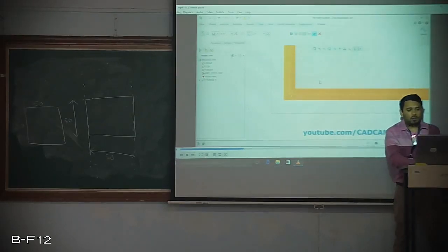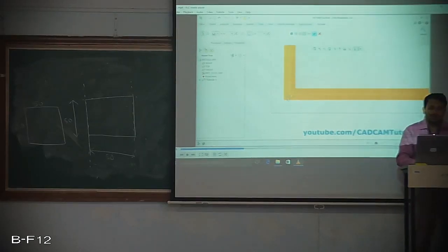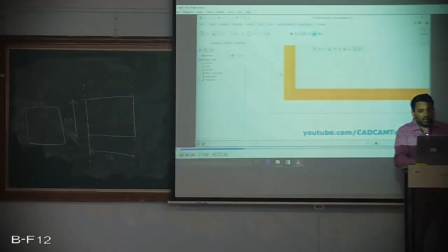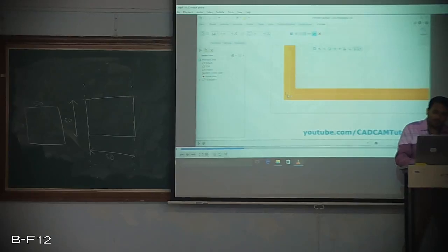Now, this is a sketch and I mentioned the thickness as 2 mm. Once it is mentioned, what happens is that outside the sketch it will take 1 mm and inside the sketch it will take 1 mm. So if I click it one more time, this entire edge will be pushed inside. That means the thickness that is added, it is added inside this sketch itself.